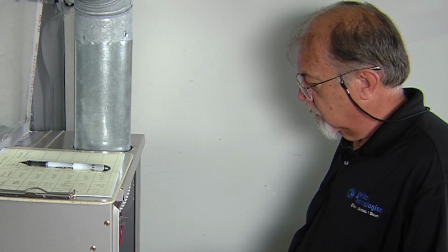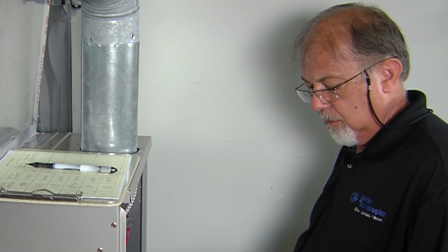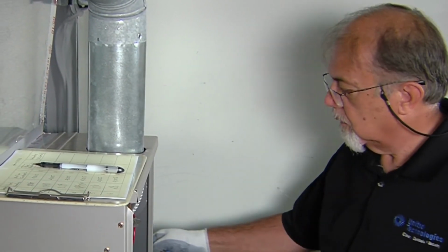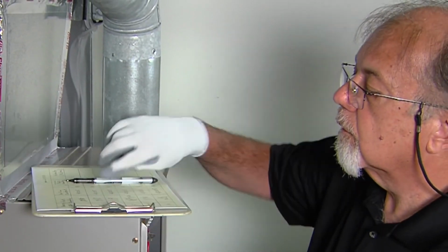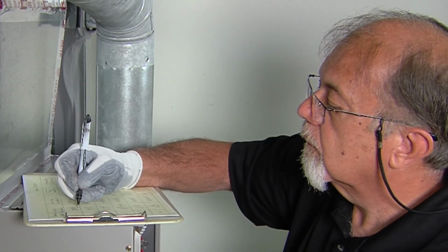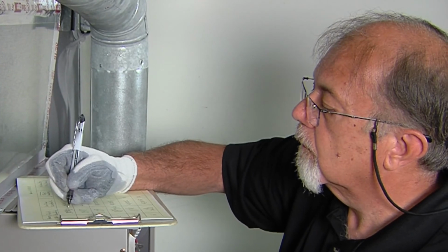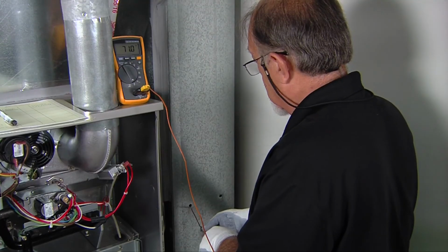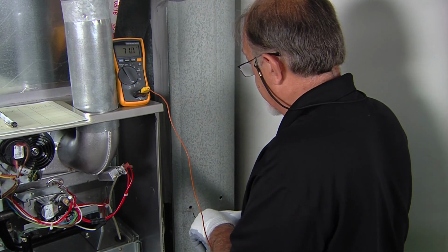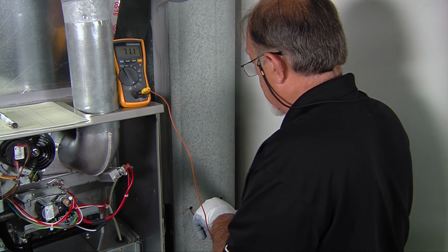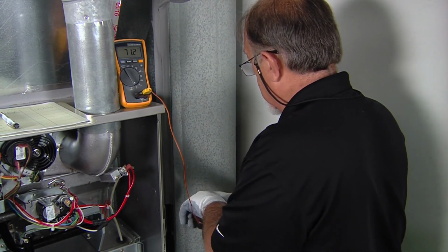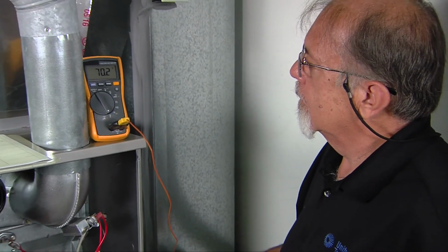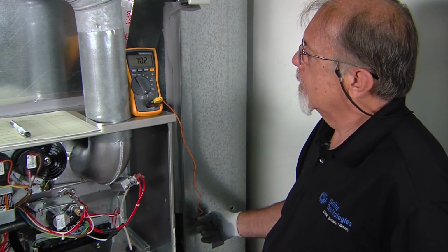Record each pitot tube reading on your data sheet. It doesn't hurt to take the time to take a second set of measurements to compare to your first set of measurements. Be careful to record all your readings accurately into your table. Now measure and record the temperature of the air in the duct system. We will explain why this is necessary in our next video, calculating CFM.